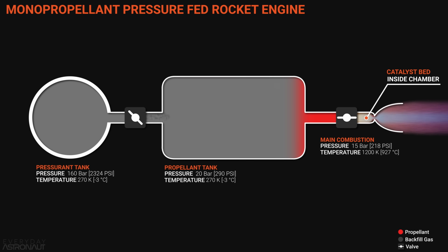And here's where we still have to have a very high pressure COPV storing a lot of high pressure gas in our pressurant tank. Now, a lot of thought also goes into just how big to make the throat of a nozzle, as the size of the throat basically lets us know how much pressure will build up inside the combustion chamber. So if the throat is too small, there actually is a risk of pressure going back up the system. And of course, that is bad.